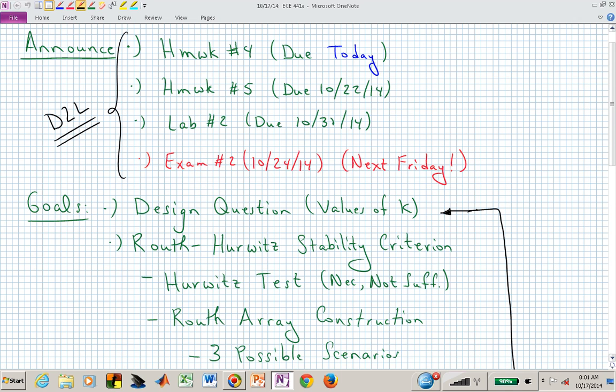So you maybe can start looking at the demo this weekend or looking at what's needed. But essentially that one is you're moving the closed loop poles by full state feedback. You're feeding back position information, you're feeding back velocity information, and that now allows you arbitrary movement of your poles in the complex S-plane. And you should, after what we've talked about with design specifications, understand how those pole locations impact your performance in the system, how they impact settling time, percent overshoot, peak time, etc.